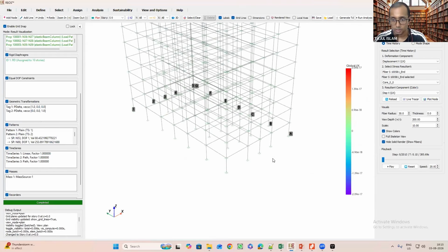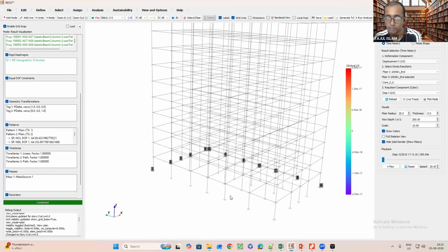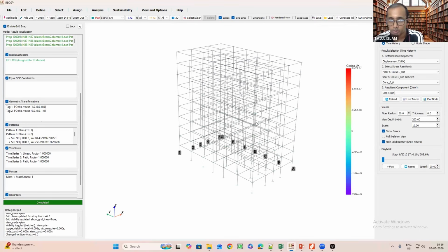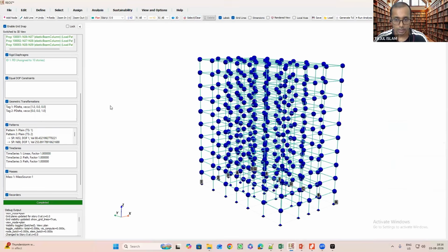It was implemented for the force beam column and the beam with hinge element. Since we have assigned the displacement beam column element, it is not working for this element. So we'll look into this and update accordingly. I'll show you using the other element. Now before that, let me show you the time history analysis as well.